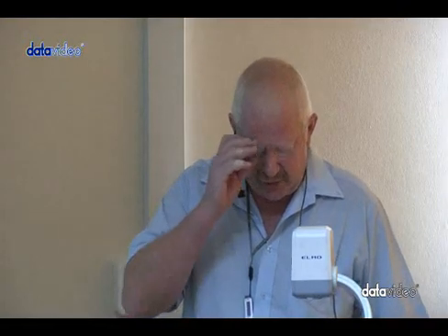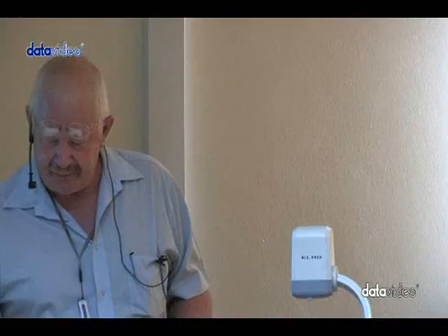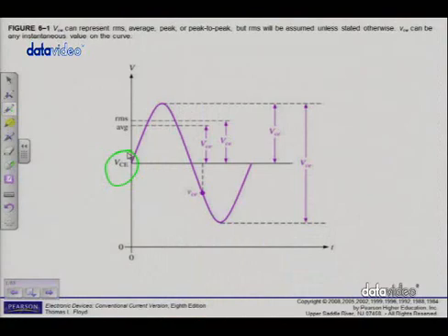Alright, but before we get there, still on page 257, just to make sure that we understand the names that are used for the quantities in this book. AC quantities, you are familiar with the DC quantities. If you can recall from previous chapters, DC quantities like VCE, we can see that the subscripts are capital letters. That of course refers to a DC quantity. If we look at these AC quantities like Vce peak to peak, for instance, I can see that the subscripts are lowercase to indicate that these are AC voltages.